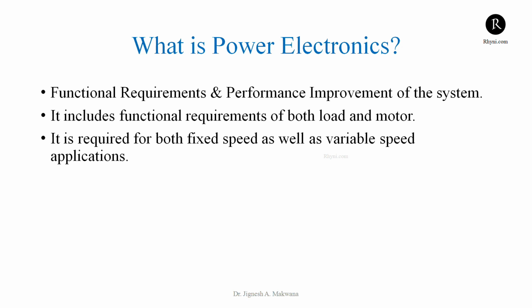It is also required for the fixed speed drive because of the type of motor, right? For example, a fixed speed drive requires power electronics to convert AC into DC, while motor is DC and available supply is AC. Similarly, when AC motors need to be used on portable devices, power electronics is required to convert DC into AC.